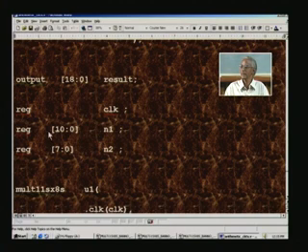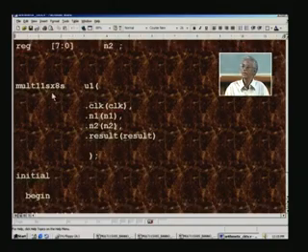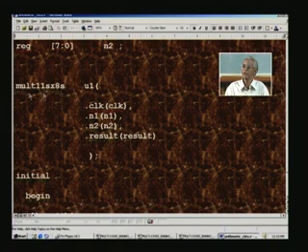We have seen that n1 is 11 bits, with the 10th bit being the sign, and so is the case with bit 7, which is also the sign. This is 8 bits for n2. And we invoke the design here, mult 11s into 8s. This is the module name.